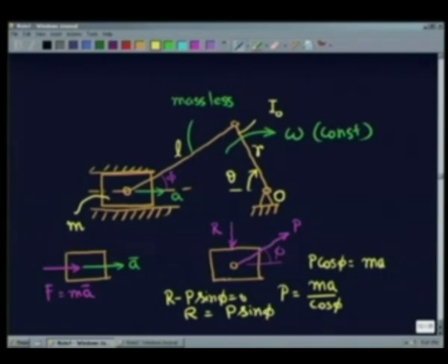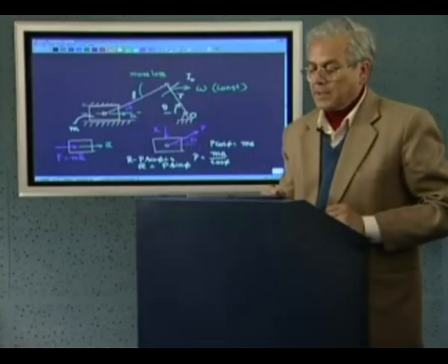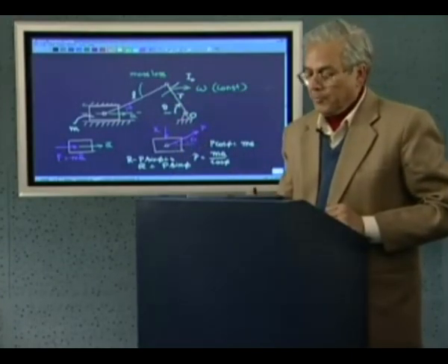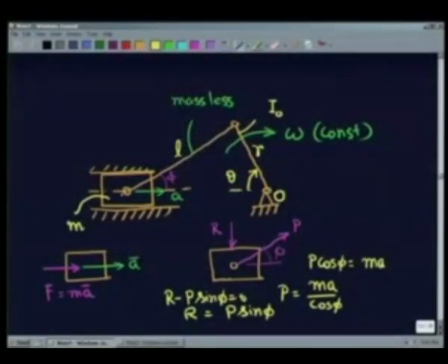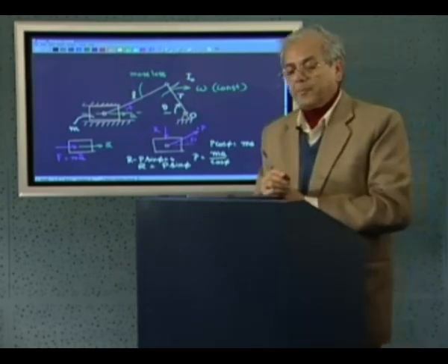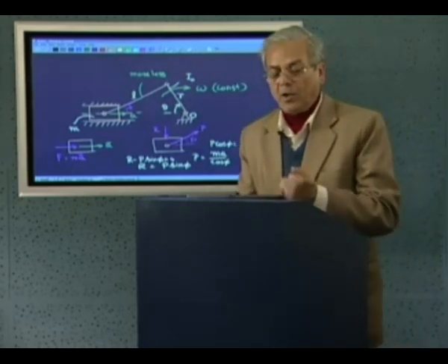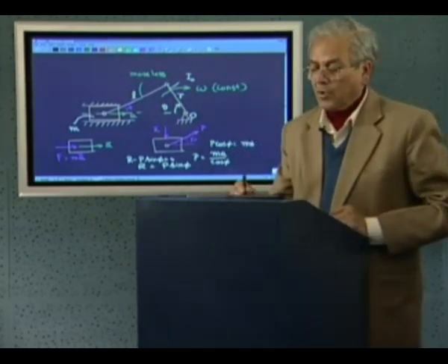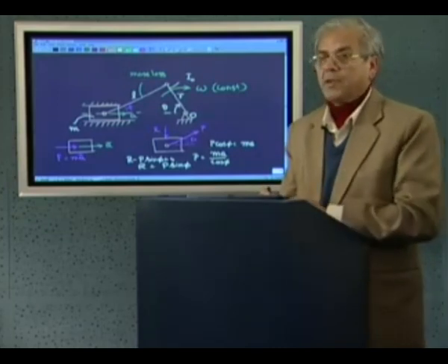So therefore we know that this connecting rod, which is massless in our example, has a force P in this direction. So obviously here also, it must be acted upon by an equal and opposite force P, so that the rod is under no resultant force. Now this is a particular example, and we solved the loading on the connecting rod as just a simple case of example.